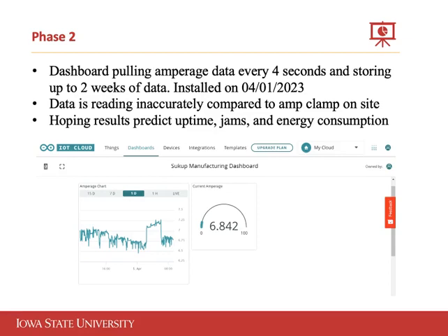Through a root cause analysis, we were able to figure out the problem was the breadboard, the main infrastructure for the wire connections. The issue was a breadboard could only transfer around 5 to 6 amps through its system. This was why our system was maxing out around 6 amps. And so our recommendations to Sukup are to use a proto board or a PCB board.